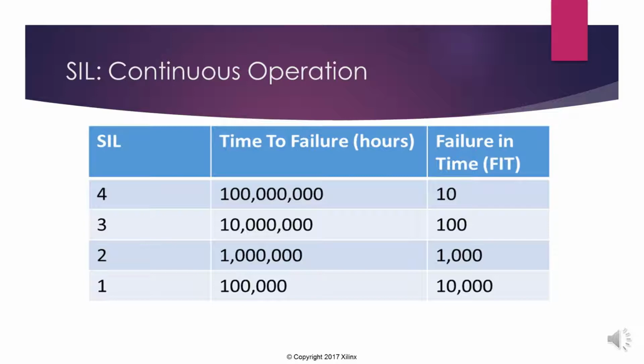So it's very difficult to actually create a well-architected solution for the higher SIL 3, SIL 4 levels that demonstrates this failure in time, and we're going to have to use redundancy, hardware fault tolerance, and good design techniques to achieve this.